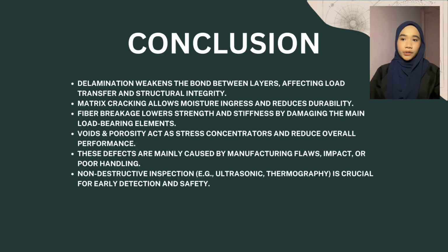So, for the conclusion, delamination weakens the bond between layers, affecting load transfer and structural integrity. Matrix cracking allows moisture ingress and reduces durability. Fiber breakage lowers strength and stiffness by damaging the main load bearing elements.